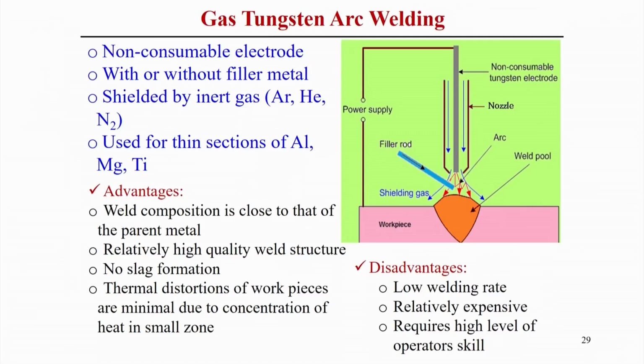This is one of the simplest welding processes, but also a very usable one, with typical advantages: since there is no need of a consumable electrode, or any filler material, the material is joined only by supplying heat and fusing the two materials.